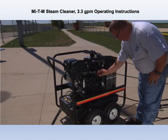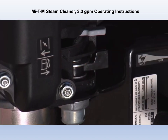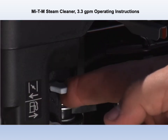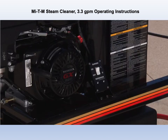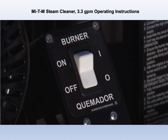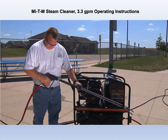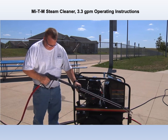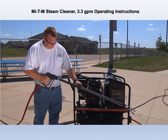Turn the engine switch on and the gas lever on. Slide the choke lever to the open position and the throttle lever to the left, or the full throttle position. Make sure the burner switch is in the off position. Holding the gun assembly firmly in your hand, point it in a safe direction and squeeze the trigger to release the pressure. Failure to release the pressure will make it impossible to start the engine.